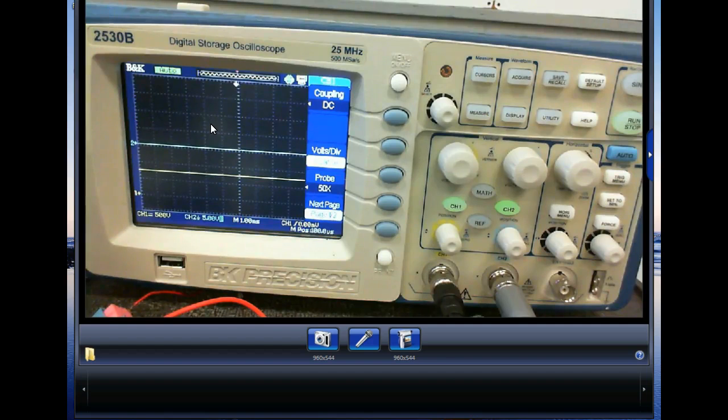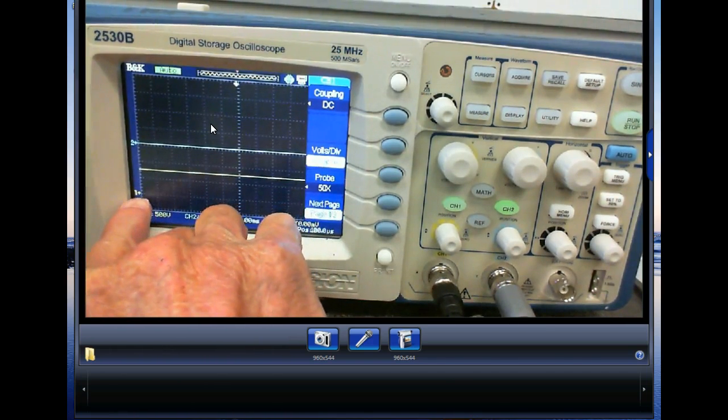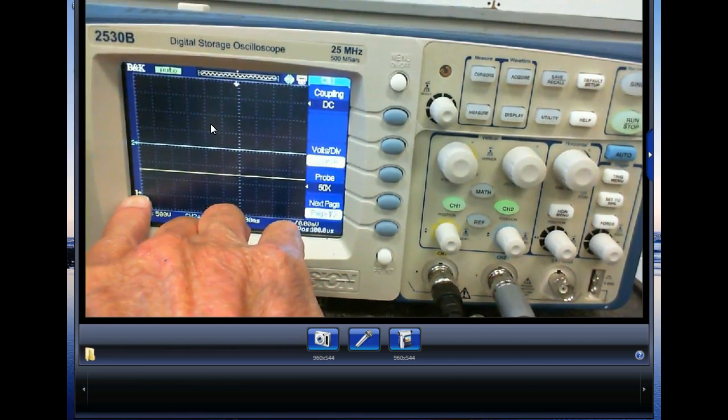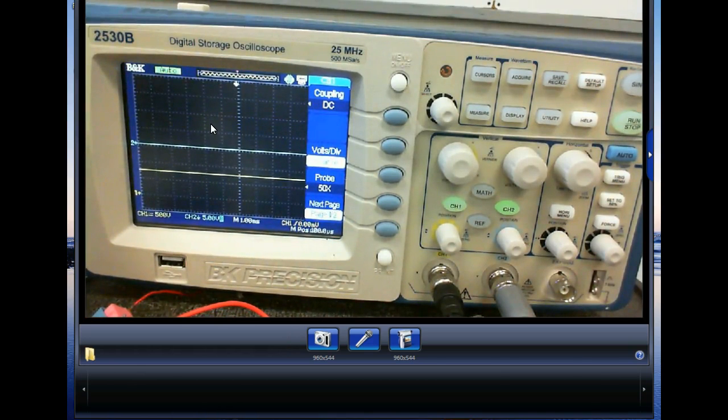Does that make sense? On digital scopes we don't have that problem because it has a thing over here that shows us where zero is at. So you can still keep the other ground. Well, no, it connects to ground through the scope. So no, both parts are ground. Well, the tip is not grounded; it's switched over to ground. Okay. So you're not going to blow stuff up if you switch it to reference. So what it does is it takes the tip and switches it to ground. Not the tip, the circuit that feeds the tip.